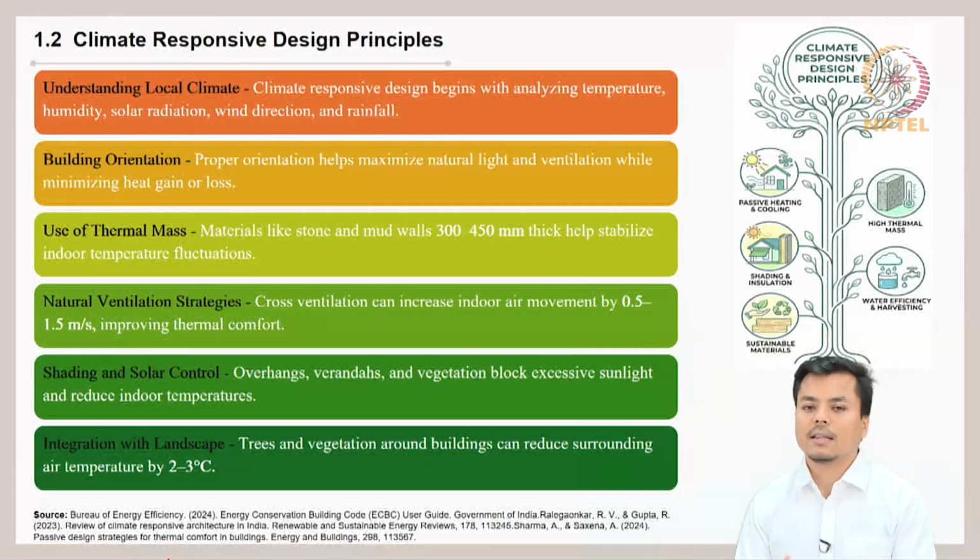Today, since the availability of land is not such that you can design verandas all around the specific building, that is where these buffer spaces like toilets and balconies have to be designed in these directions, not towards the direction from where there is direct sunlight. So these are some strategies that are applied to minimize solar heat gain in such extreme weather conditions.